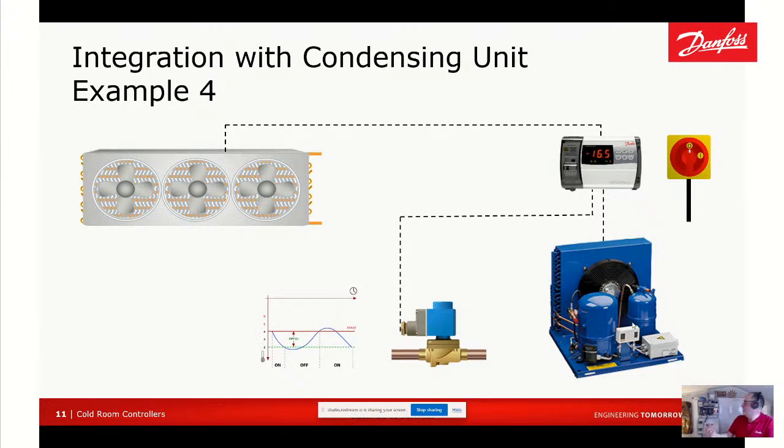Now, the panel behind me has got contactors in. This is actually a 3-phase panel, so this can cope with a bit more load. We'll come a little bit further down in the slides and we'll see the single phase version, which doesn't have contactors, it just has relays on the board. So it depends on the application, the duty, and the size of the equipment as to what you actually need in your control panel, and in real terms, how you're actually going to operate it.